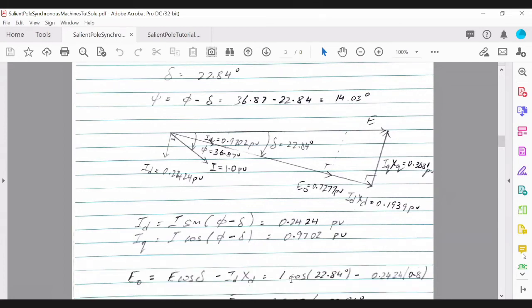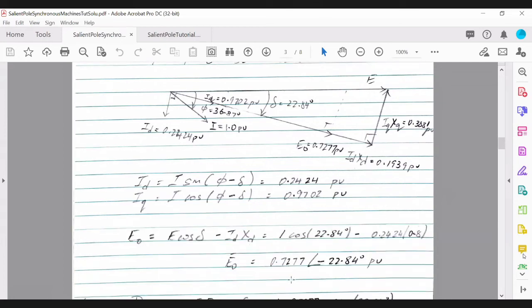Right, so from there, if we look at the phasor diagram, we can see that in order for us to determine the induced current, we're dropping a perpendicular from your induced voltage, a perpendicular which is parallel to IQ XQ, and that is basically, if we resolve this phasor, which is E along E naught, we get basically E cos of delta up to this point.